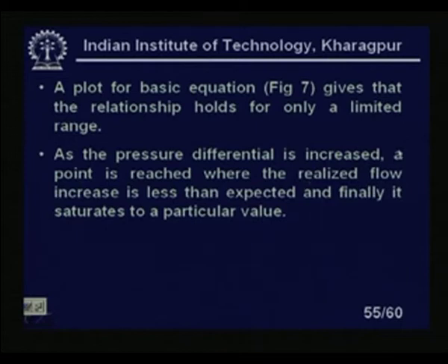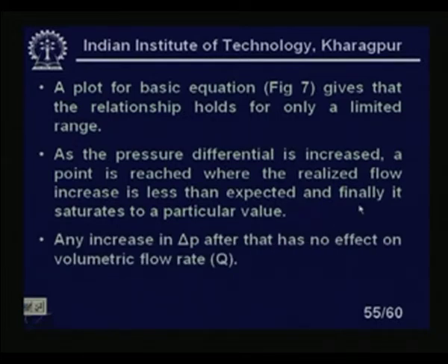As the pressure differential is increased, a point is reached where the realized flow increase is less than the expected, and finally it saturates to a particular value. Any increase in delta P after that has no effect on the volumetric flow rate. Even if you increase it, that will not affect the flow rate of the valve, unlike the stem movement, where whenever you have a stem movement there is always a change of flow.